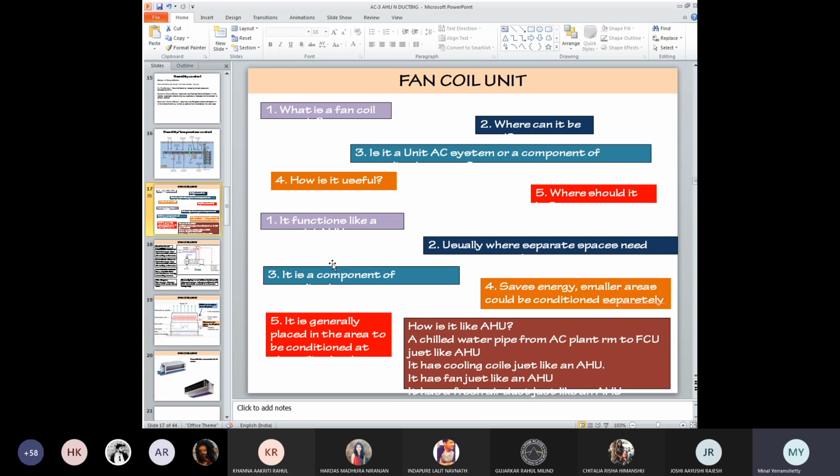So does that mean that the first set of people who are still staying there, because they are on site, they will go leisurely, will they not receive the electricity or the AHU or the AC? No, they do get. That's where my FCU comes in. It is still centralized, but I can completely control because of this fan coil unit.